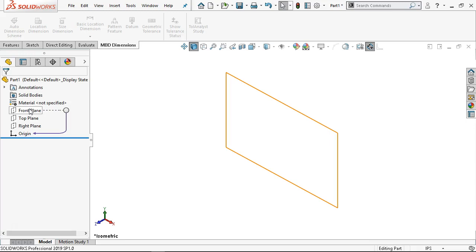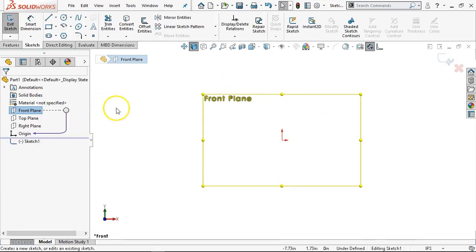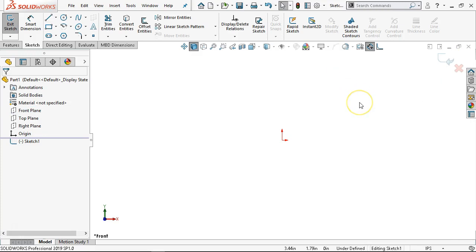So on the right mouse button, let's see if that's working correctly. If I single click on the plane, it should come up with that pop-up, except my mouse is, there we go. I'm doing the button happy second click that lets me rename it. The top left, if I hover over that, is telling me that it's a sketch. And as soon as I go into the sketch, I can tell that I'm in a sketch because I have the red origin, and we have the confirmation corner in the upper right. And once I click out, I'm going to see that plane go away that I don't really need.